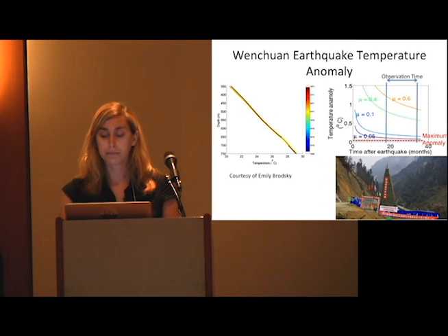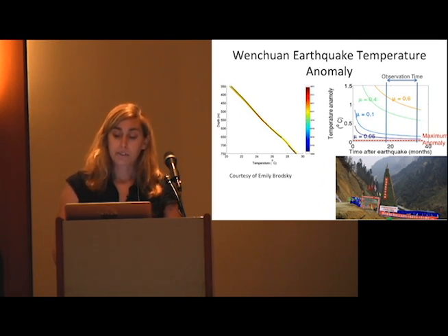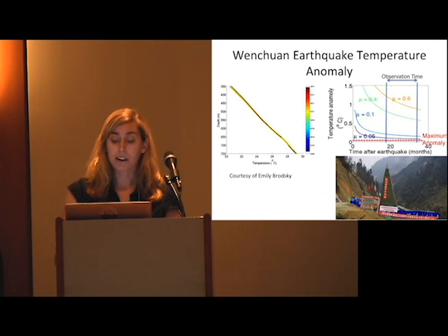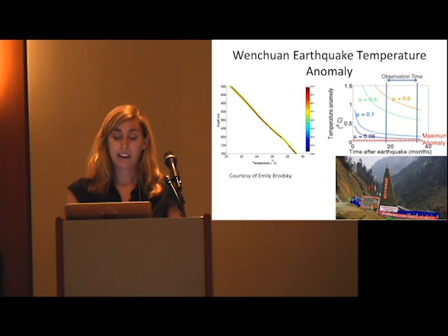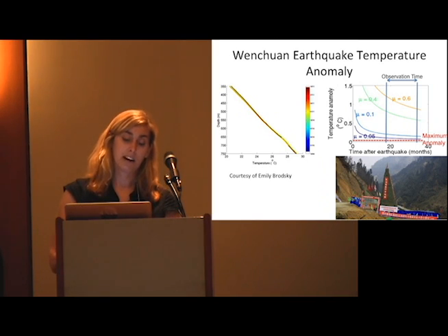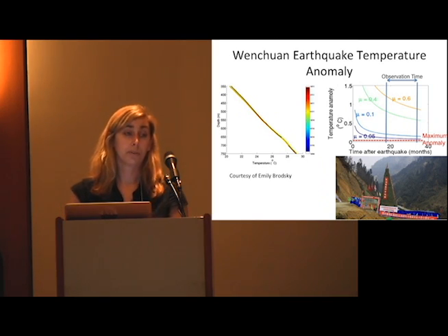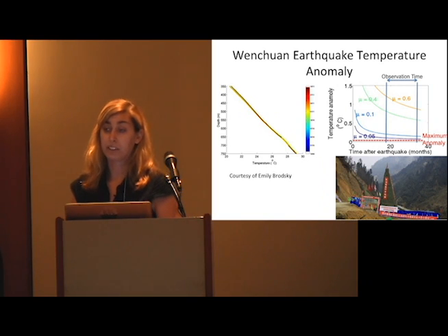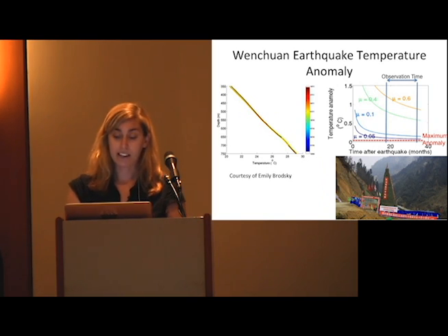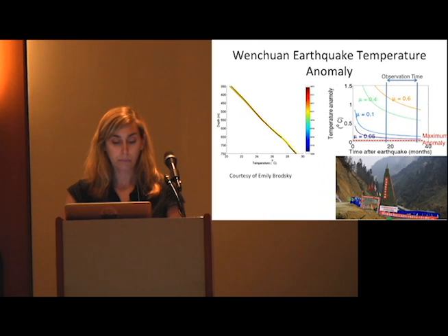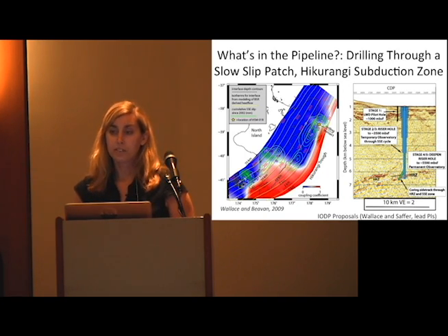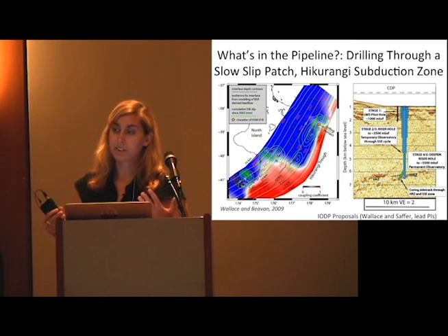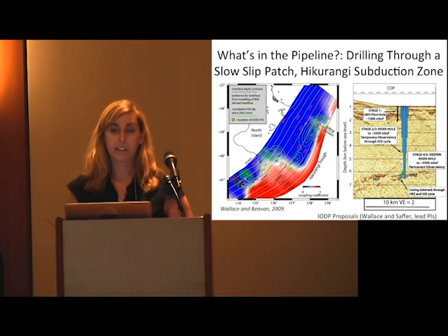And if you model that, you'd find that it requires the coefficient of friction during the earthquake to be below 0.05. And if this doesn't actually end up being an anomaly related to the earthquake, then it has to be even lower than that. So it's sort of a fascinating result. Those were all post-mortem, so post-earthquake kind of work that you could do.